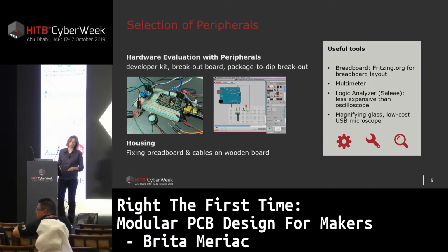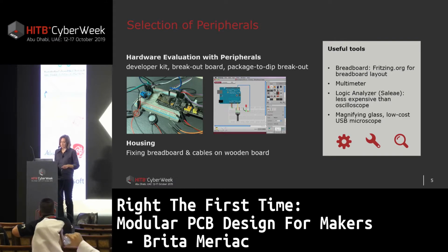So microcontrollers and most peripherals are available as developer kits, or at least as breakout boards. You can plan your connections with software tools like Fritzing.org. This is very helpful to create your basic setup and have a breadboard view for it, so you can connect it accordingly. And this might be already enough for a lot of projects, and you might want to stop here. But if you implement these things on your own custom PCB, you can enhance your project a lot.